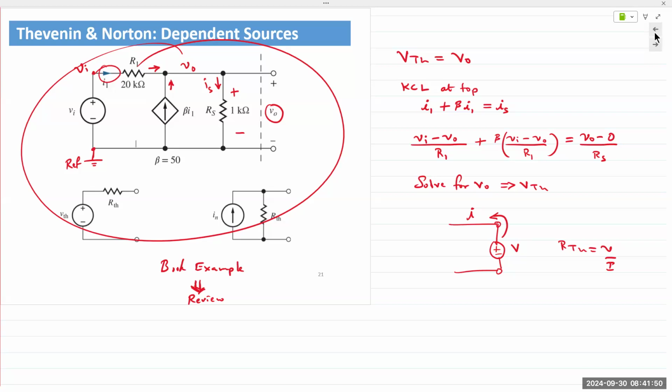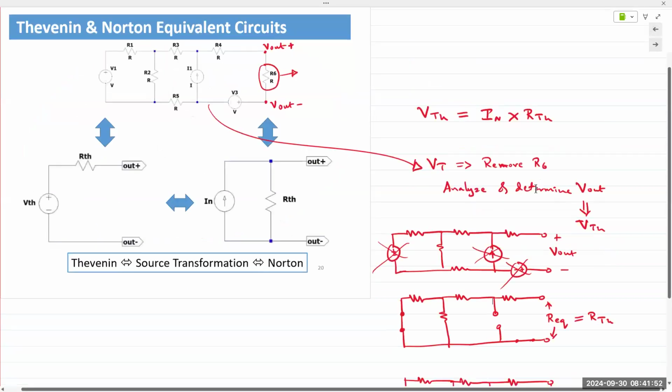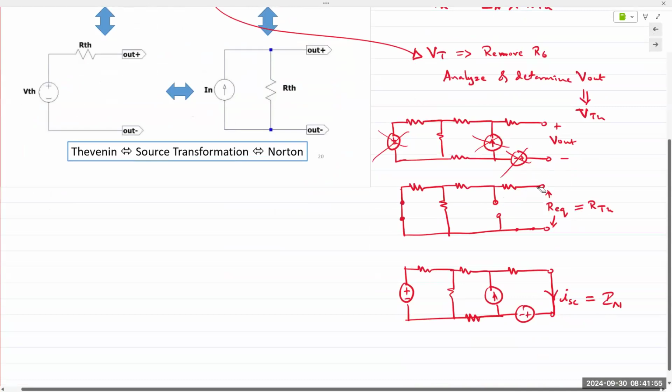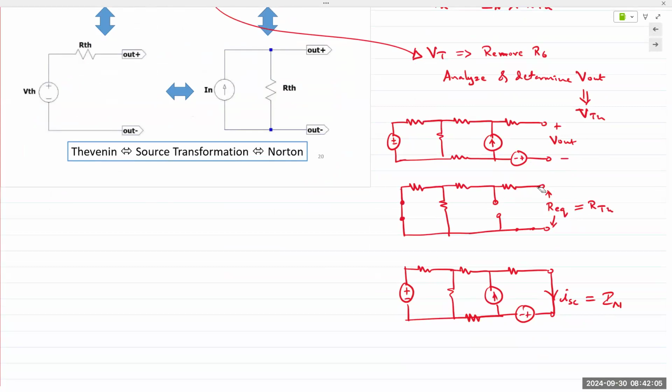But again, let's back up. So in the quiz, I had 3 components listed. Each one of those components, meaning find the Thevenin, Norton, and Thevenin resistance as seen by that component. You remove that component from analysis, meaning that's the load. It doesn't matter that it's the voltage source. You remove it from the circuit. It leaves behind 2 open terminals. Those terminals are where you would analyze for Thevenin voltage, for Norton current, and Thevenin resistance.